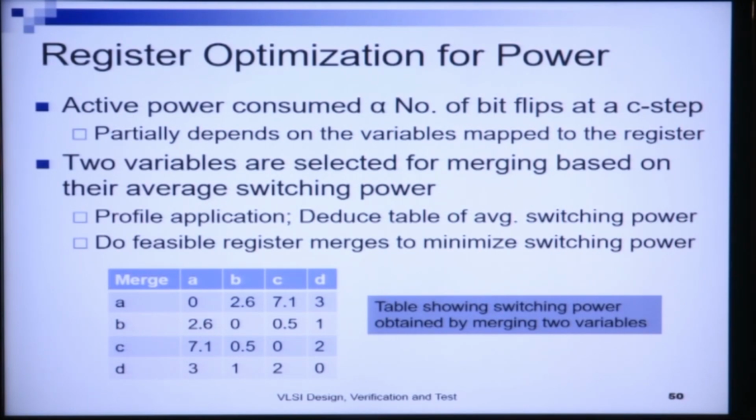So in this temporary variable, the values of the lower order bits change more. And I have another temporary variable in which the values of the higher order bits change more. Now when both these variables are kept together in the same hardware register, then overall there will be a lot of bit flips when these two variables are kept in the same register, right?